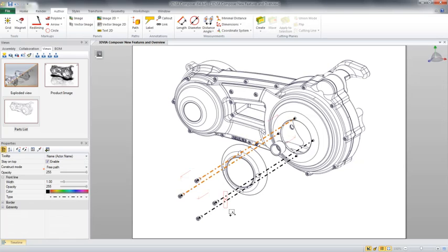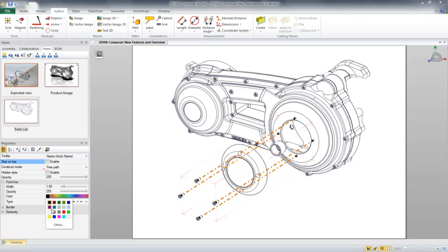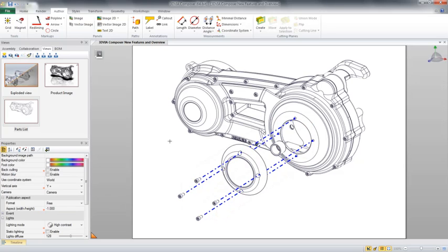In this case, we're going to select the 4 trail lines and change some of these properties in the lower left. We're going to change whether or not it stays on top or visible through geometry, and the color. We could also change things such as the line type style that we want to use, as well as width, opacity, and many other properties.